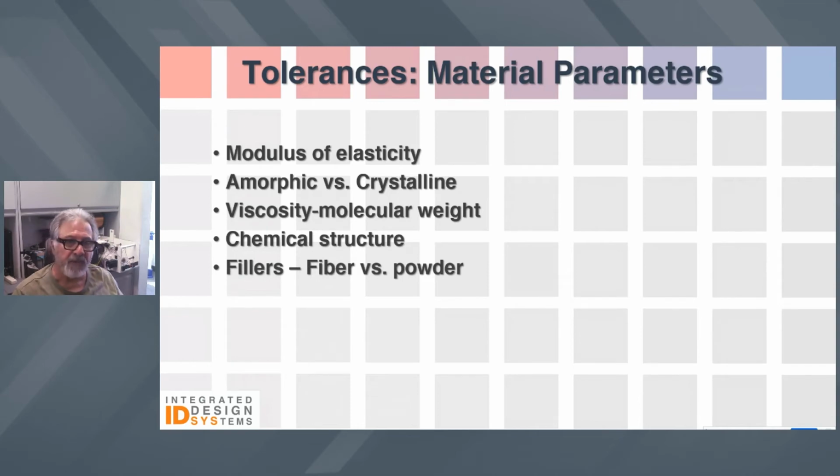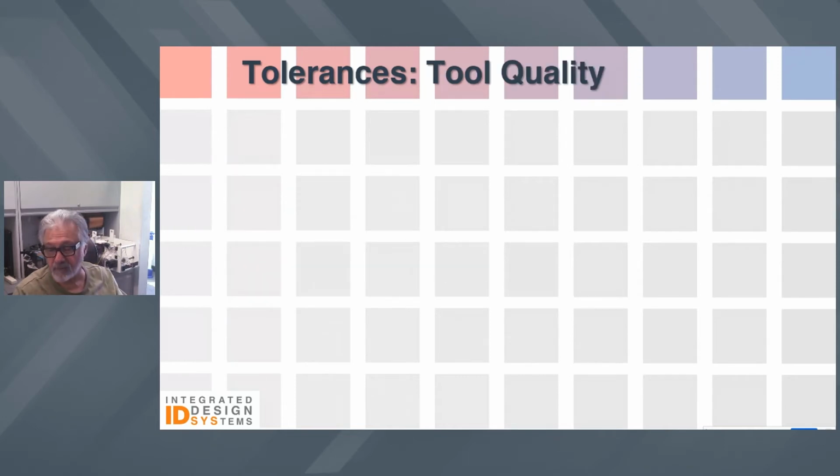fillers versus powders, because when you get into materials that are like glass reinforced plastics, for instance, there's an orientation to the fiber ratio of length to diameter, which will change the rigidity of the plastic as it flows through the mold and also alter its shrinkage and ultimately its tolerances, versus a powder or a filler, which is symmetrical all the way around. It's essentially a sphere. And the fillers tend to essentially occupy volume and improve the repeatability of the tolerances during manufacturing. This is typically done with polypropylene, for instance. They often add fillers to improve its moldability.